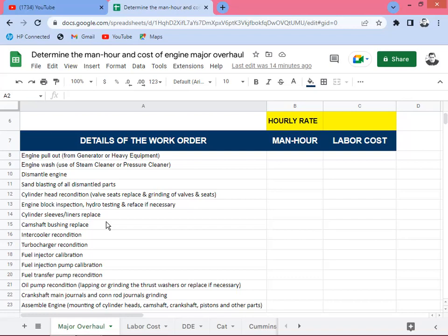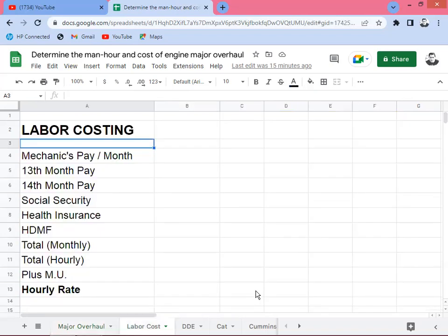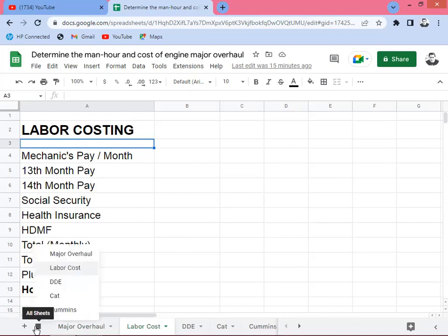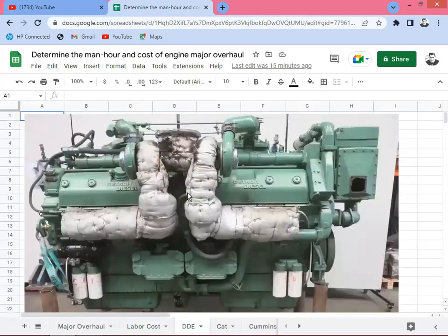So the Detroit Diesel engines, they call them liners, and engines like Cummins, they call them sleeves. The sleeves will have to be pressed to remove them, and pressed again to install them, unlike the liners, which can be removed by hand. Okay, and I'd like to show you the engine that we're going to be doing. It could be the Detroit Diesel.